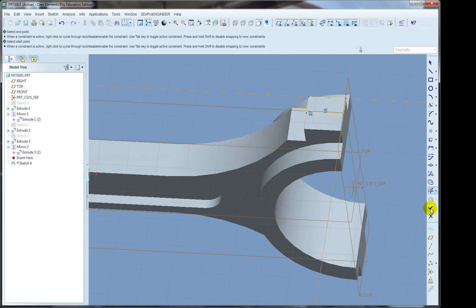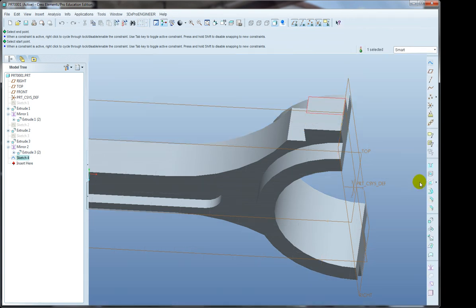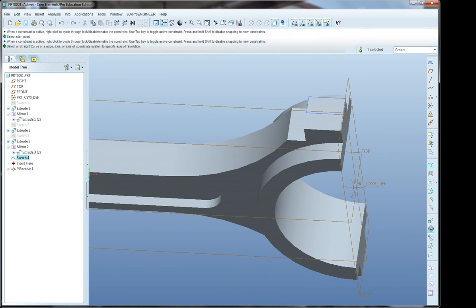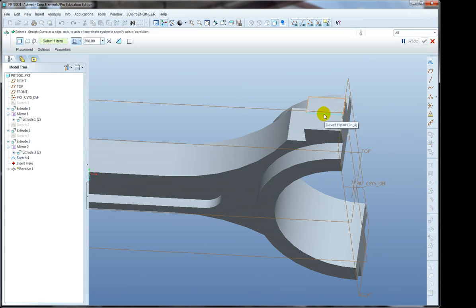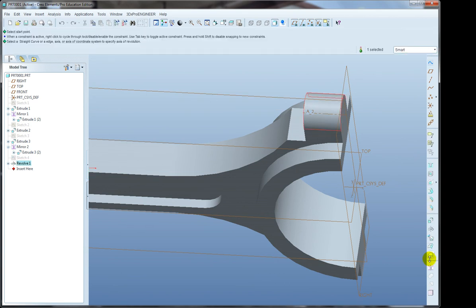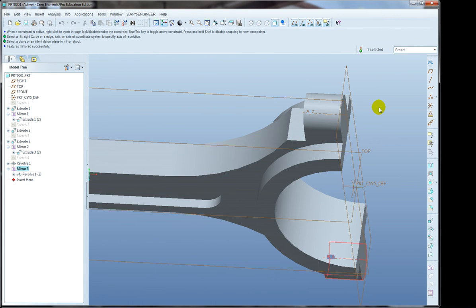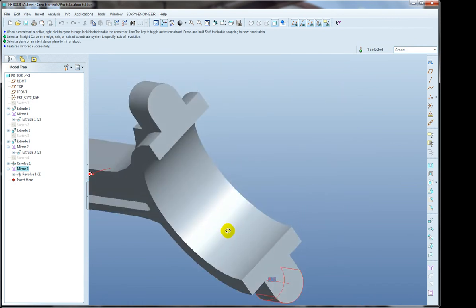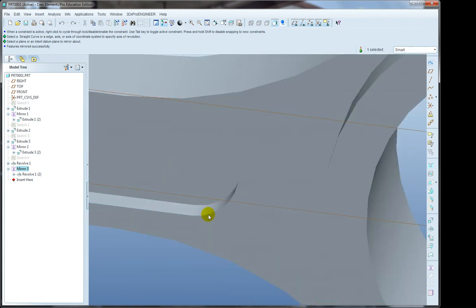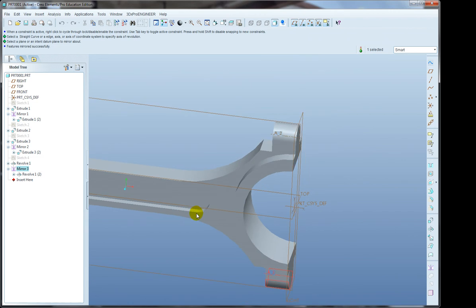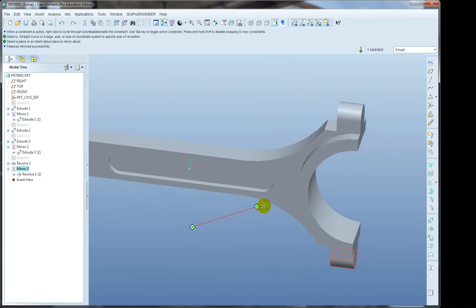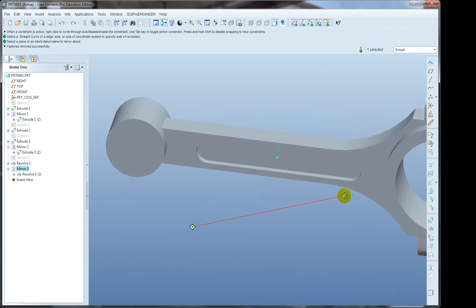I can now finish this sketch, and instead of Extrude, I'm going to select Revolve, with this being my axis, and I only want this to go 180 degrees. Now I can finish this, click Mirror, grab my plane, hit the checkbox, and now I have it on the opposite side as well. So now, as you can see, I've got all of the features in this object that I need to have, minus the holes.